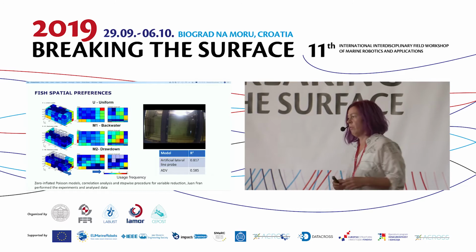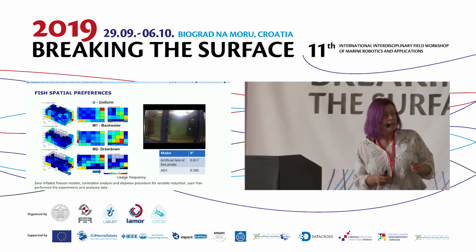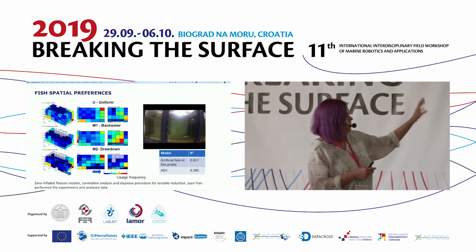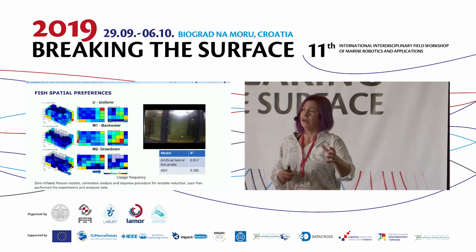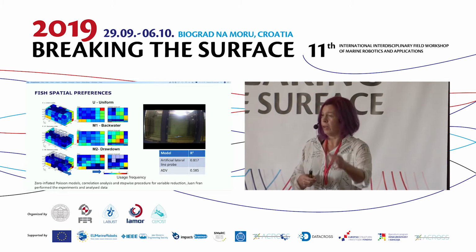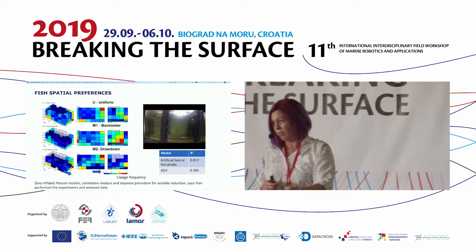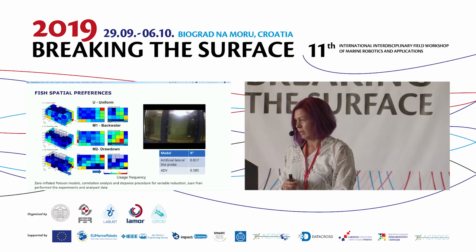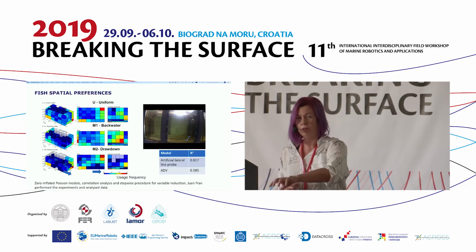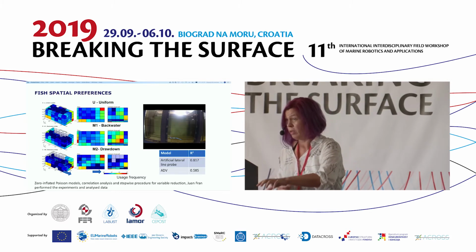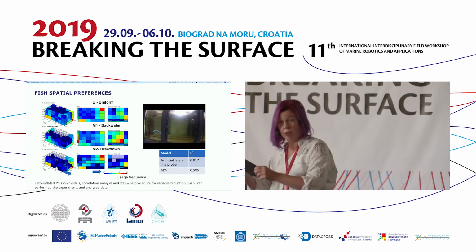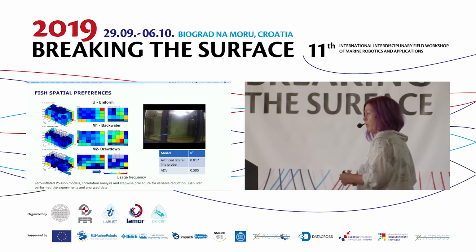And we got a lot of interesting new knowledge on that. So if you look at this one, now also the sensors are Eulerian sensors in a way, so they are point measurements. We put it in a certain place on the ground, and then we stay there and we measure. So water is moving, but we're staying at the same point, as opposed to fluid dynamics, where you go to Lagrangian measurements. Lagrangian measurements is as if you were a particle and you were going together with the fluid. So you get a different view of the fluid in this case.